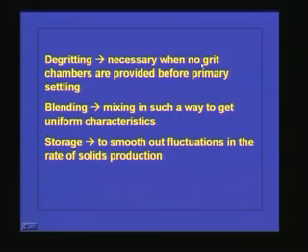So the sludge will contain both organic and inorganic solids. If the grit or the inorganic solids are present along with the sludge, what will happen? The pumps we are using for sludge pumping will be affected by this grit. So it is very essential to remove the grit, or the heavy inorganic material present in the biosolids. It is necessary when no grit chambers are provided before the primary settling. The purpose is to remove the grit present in the biosolids.